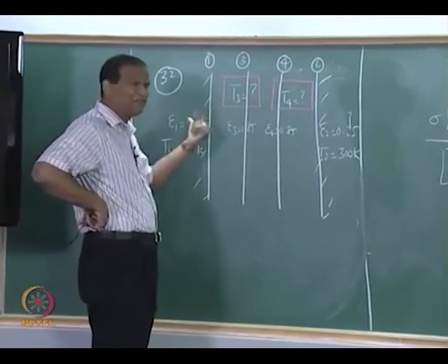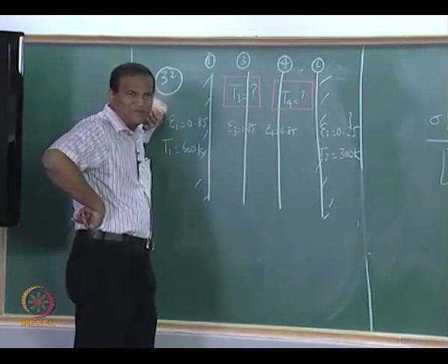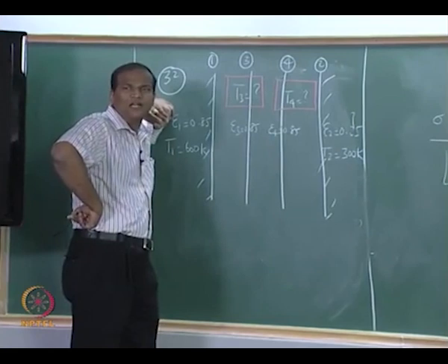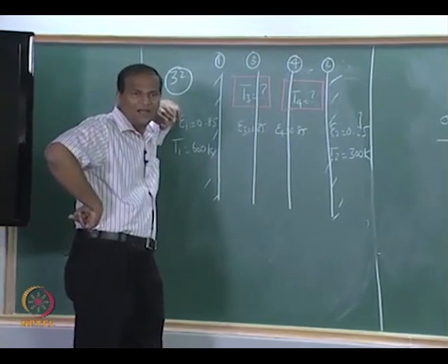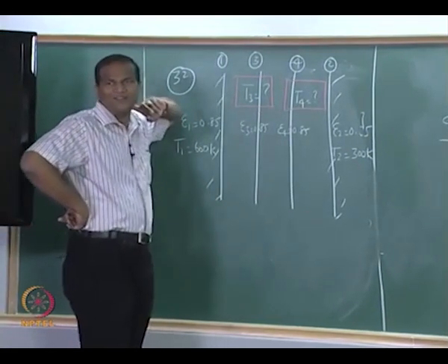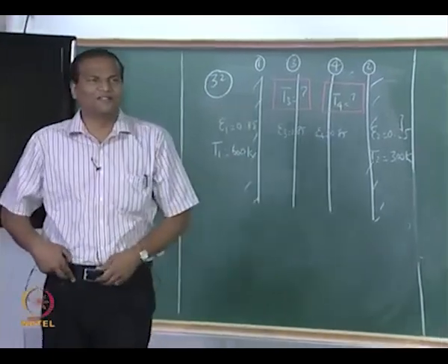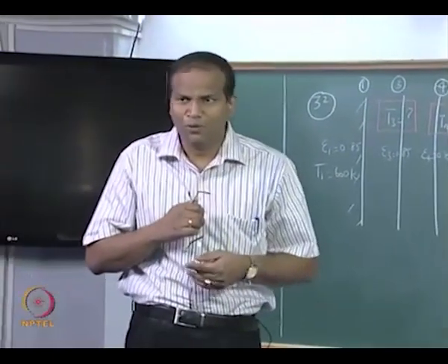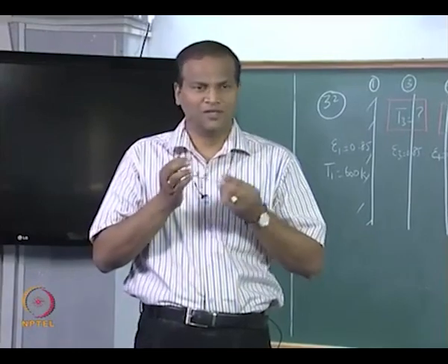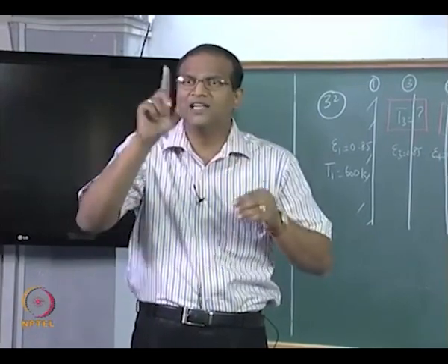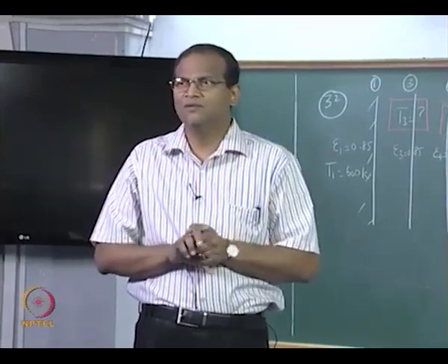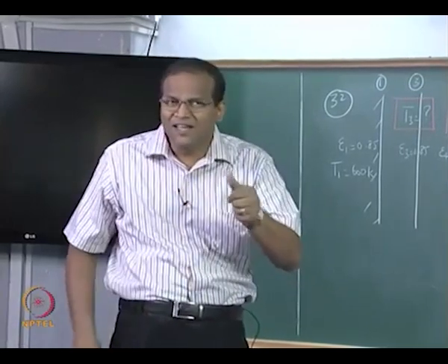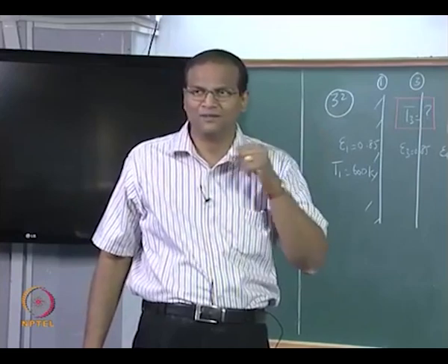And if each of these is different from epsilon 1 and epsilon 2... what he is saying is he is qualifying whatever I told a little earlier. I told you they have to be black, but he says so long as all are having equal emissivity, whatever I told, T1 to the power of 4 plus T2 to the power of 4 divided by 2, whole to the power of 0.25, holds. That you can call TEQ, the equilibrium temperature. In fact, a re-radiating surface will also behave like this.